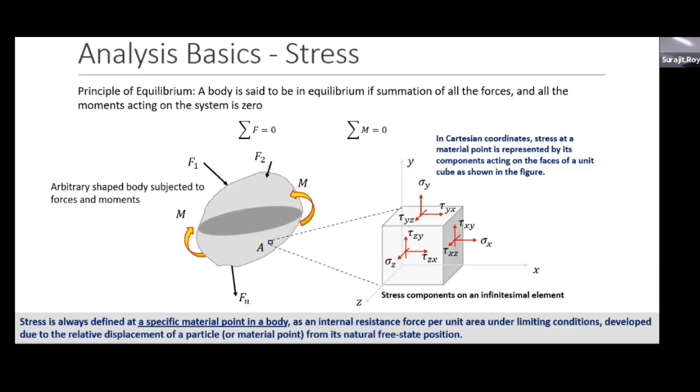Does somebody know what factor of safety people use in the aerospace industry? I believe I looked it up the other day. It was 1.5 to 2. Actually, 2 is very high. Generally, it's 1.25 to 1.5. They work in very close margins in aerospace structures, because they have to be very thin structures, whether space structures or commercial plane structures. Those structures have very good confidence in the design. You can see that 1.25 is a very small number, as close to 1 as possible.